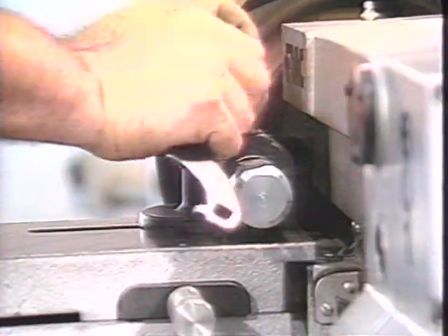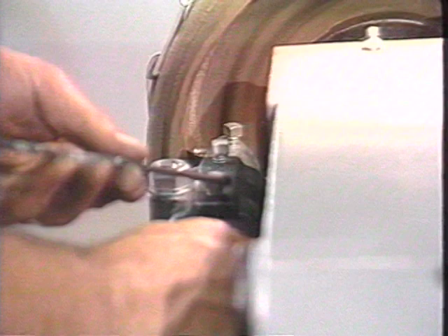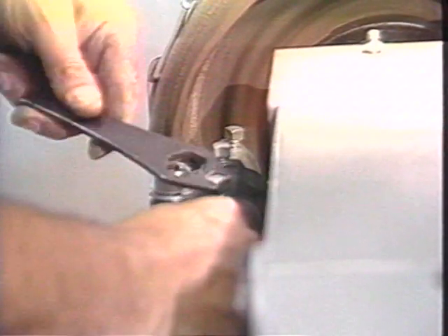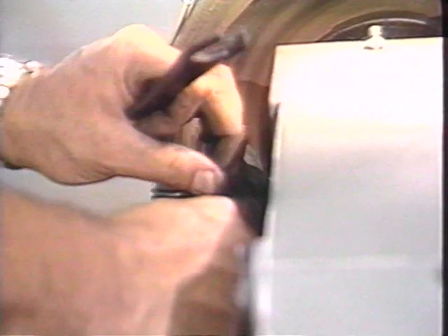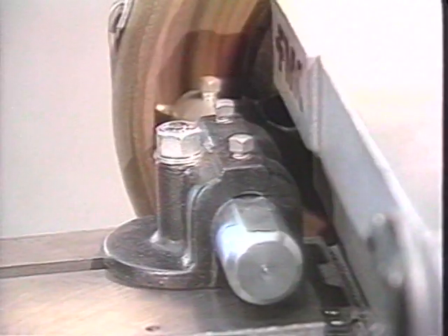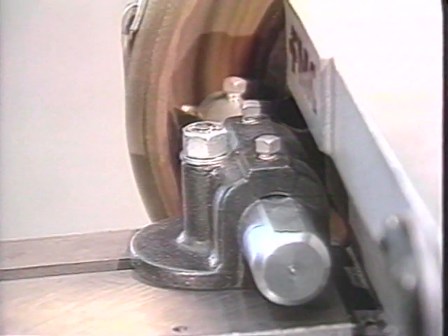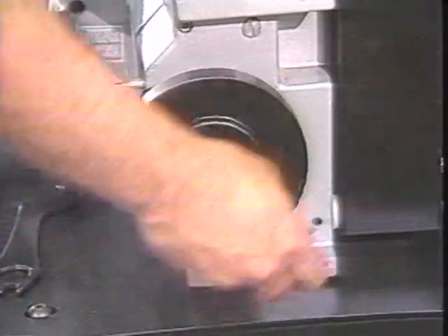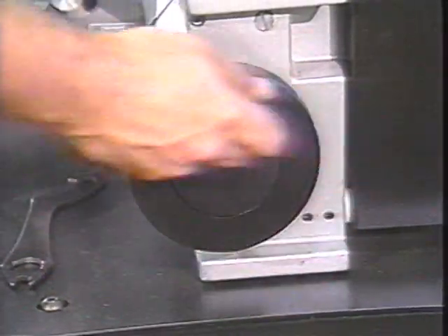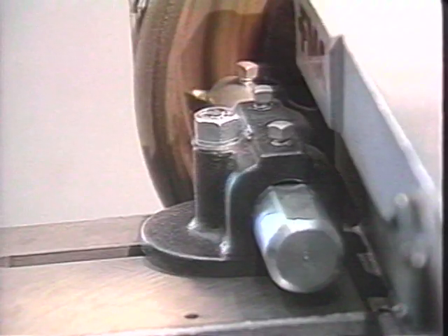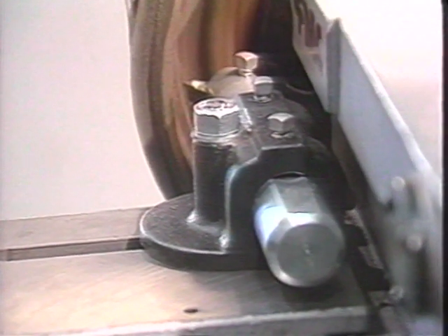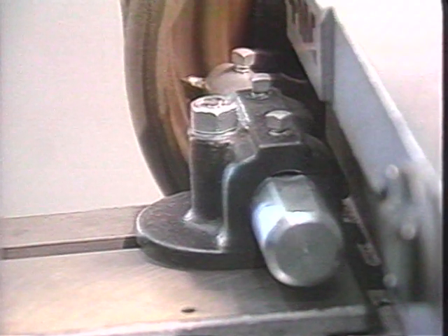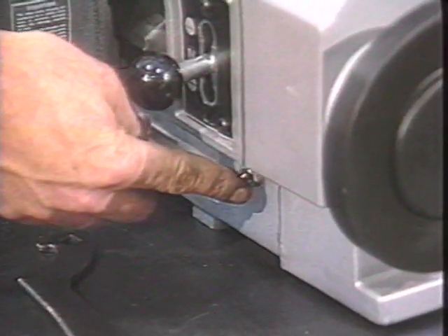Loosen the set screws and slide the cutting tool until the cutter tip is all the way to the rear of the drum face. Tighten the set screws while slightly rocking the cutter tool front to rear until the cutter tool is tight. Move the cutter tool away from the face of the drum by turning the cross slide crank. Turn the carriage hand wheel until the cutter is positioned roughly 1 inch from the edge of the drum face. This should be the same position that you measured or marked during the drum measurements.